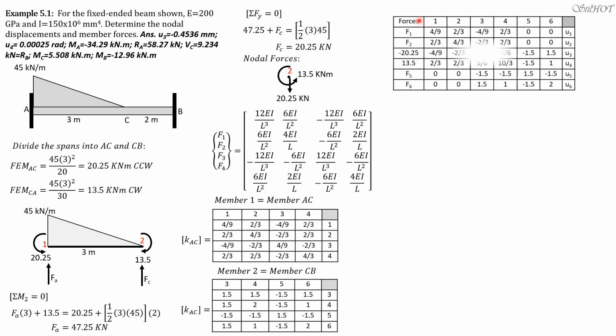So we have here the general matrix, supposedly. This is 1, 2, there are 3 nodes, so times 2, so 6. The matrix is 6 by 6. The global stiffness matrix for the beam is 6 by 6. But we eliminate rows and columns associated with zero displacements, which are rows 1, 2, 5, and 6, because there's no vertical displacement and rotation at the supports. Then it reduces to 2 by 2.